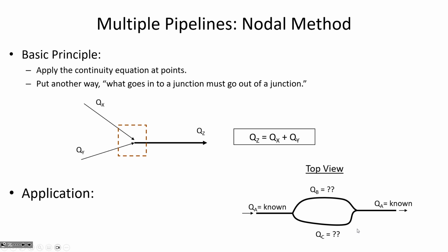a neighborhood. A lot of towns have some sort of a grid, 9th Avenue, 10th Avenue, 3rd Street, 4th Street, and so on. So if you have the water coming in, anytime the water's flowing here and going to there, it could also go from here to there. So having a grid pattern also provides you with redundancy in case there's a pipeline break. So if you just had a dead end to different parts of the network, then if one of the junctions breaks, then all of the houses downstream from there lose water. Whereas, like if this pipe broke, people here can still get the water through that route.